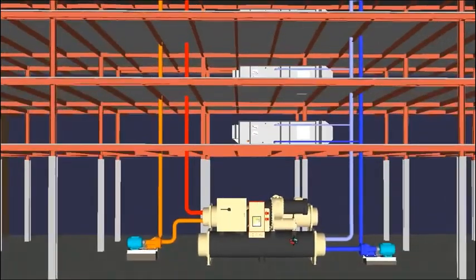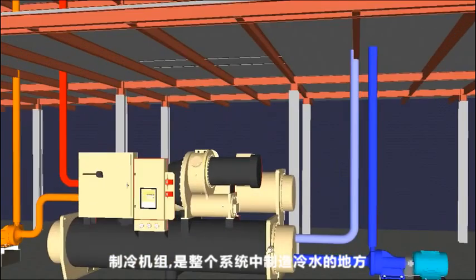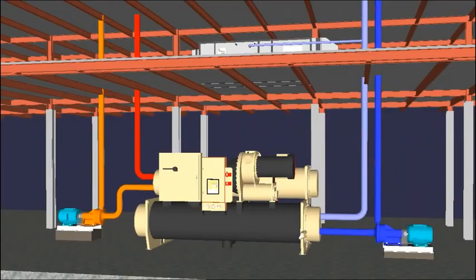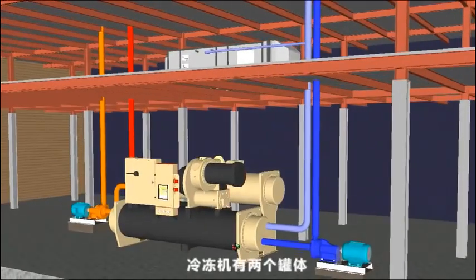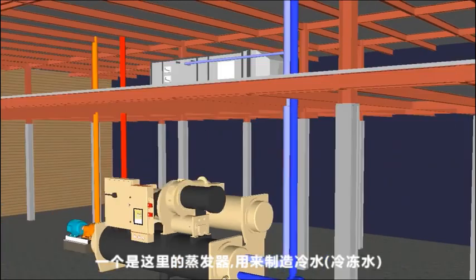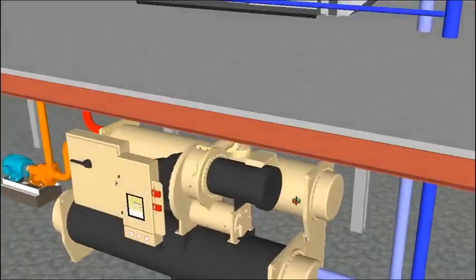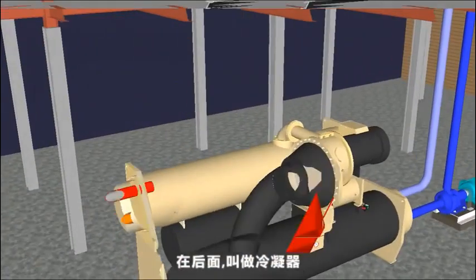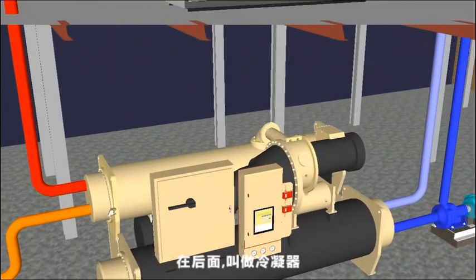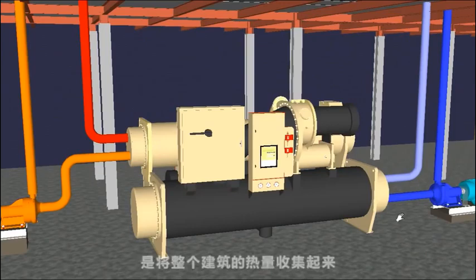So the chiller is the producer of chilled water in this system, and the chiller has two main cylinders. One is the evaporator here, and that's where the chilled or cold water is produced, and the other cylinder is this at the back here, which is the condenser cylinder, and that is where the heat of the building is collected and sent to the cooling towers.